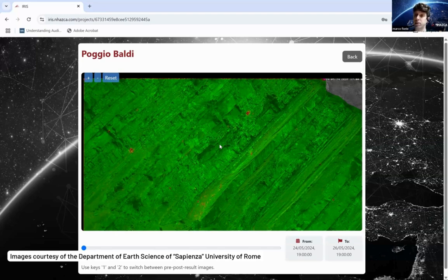And we installed a lot of sensors. We conducted a lot of site surveys, geomorphological and geotechnical. We installed both contact sensors, like strain gauges, piezometers, inclinometers, but also a lot of remote sensing instruments like total stations, laser scanners, synthetic aperture radar, and also cameras that we use to perform change detection.